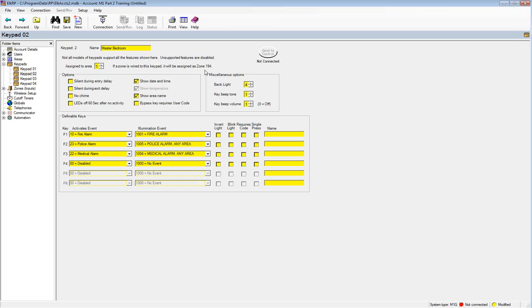So you could be doing something like maybe controlling a door lock or integrating with the garage door. These things you could add a relay to that voltage output to allow you to control those sort of things. Or if you just want maybe some kind of LED indicator, that sort of thing, you've got 50 milliamps there that you can use to drive a device like a relay or an LED.